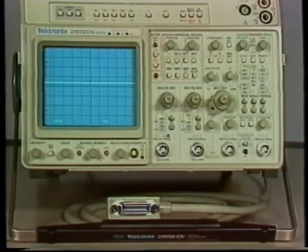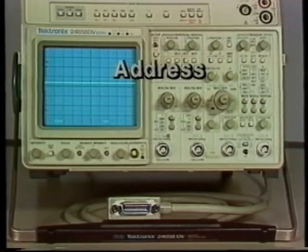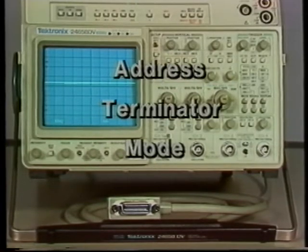The 2445B, 2465B, 2467B family of real-time scopes are completely programmable and can be equipped with a GPIB interface to communicate over the GPIB bus. We will set the scope up to operate over the GPIB bus and then verify its settings. The GPIB parameters we need to set up to enable the scope to communicate over the bus are address, terminator, and mode. These are the same basic GPIB parameters that must be set for any instrument to communicate over the GPIB bus.